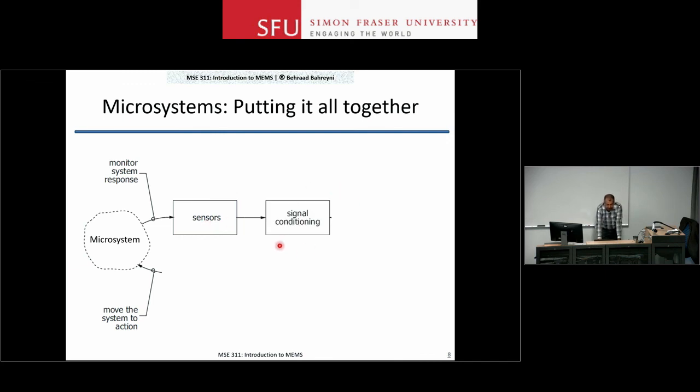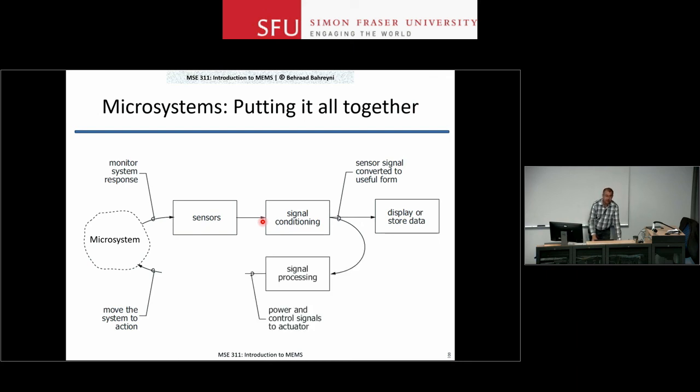There is some signal conditioning where, for example, you linearize the sensor output, or you get rid of the offsets or things like that. And then you display that data. But then in order to keep everything nice and under control and linear, you usually have some feedback where you take the output, like, let's say the proof mass of your accelerometer has displaced, and you produce a signal internally to push it back to where it was. So you will have a closed loop system where you have signal conditioning and actuators and all sorts of system components inside that one tiny package that you see.